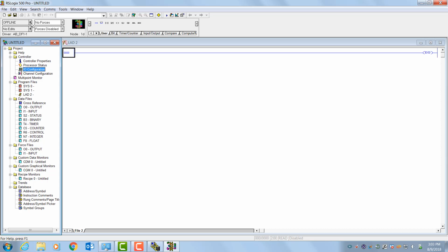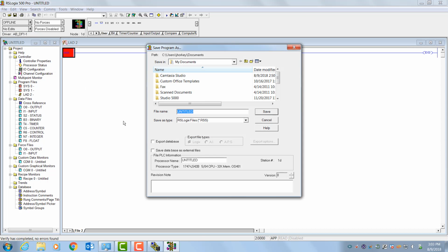And now I'm just going to download. This is just a blank program. It has no instructions. It doesn't do anything, but I'm going to go ahead and download it. This is a test that I will often do just to verify that your communication path is correct.